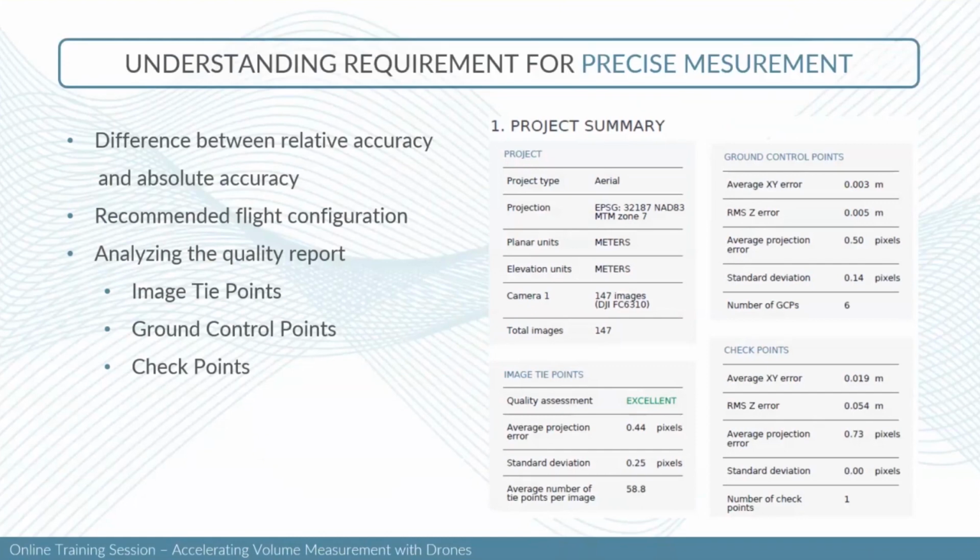If you're using ground control points, the goal here is to have a good amount of ground control points. It's really hard for us to state an appropriate number for a photogrammetric project because it depends on many factors. But you want to have your ground control points well spread out throughout your mapping area because you want to distribute the accuracy over your whole mapping product. You don't want to have them clustered in only one section of your project because the error, if there is one, will be spread out throughout all the rest of the project.